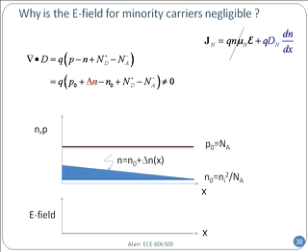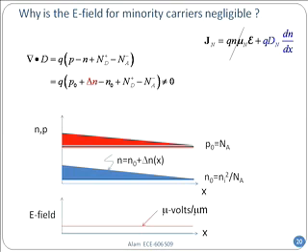So what it's going to do as a result is increase the electric field a little bit in that region, a very tiny amount, and it will pull in holes from the contacts to almost exactly compensate the electron concentration. So it's not photo-generated. It is coming in because it wants to minimize that quantity on the right-hand side. So it will pull in a little bit of holes to sort of match the profile.